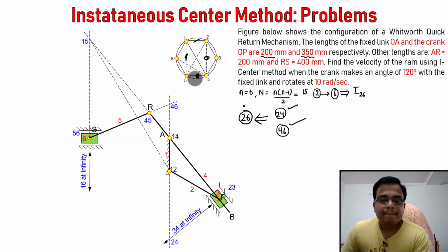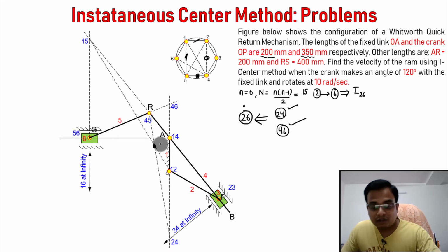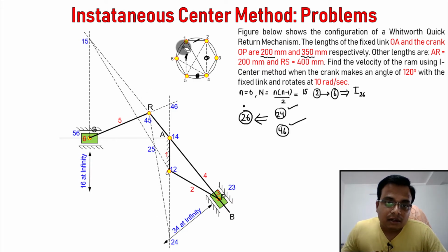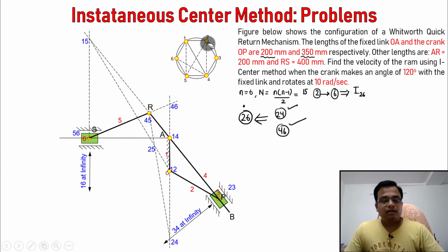So now connect eye centers 4 5 with 2 4. Where is 4 5? This is 4 5. Where is 2 4? This is 2 4. So make a line connecting 4 5 with 2 4. Here we go. These two intersect somewhere here, and this is what we really wanted. Okay, and that's your eye center. Eye center what? Eye center 2 5. That's known to us. Now let me rub the stuff. So that's done. Now we have a different approach.